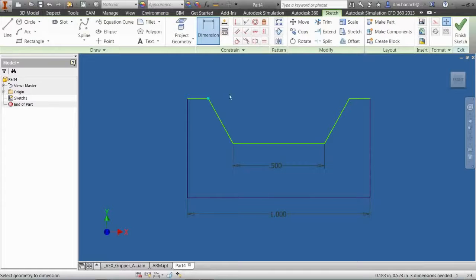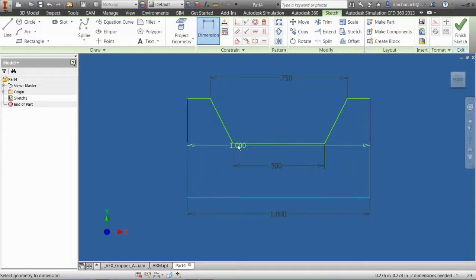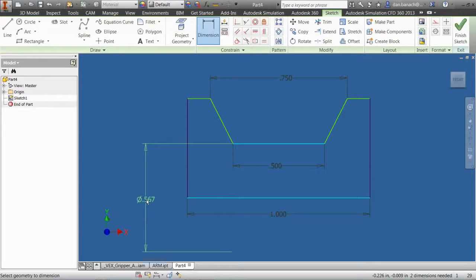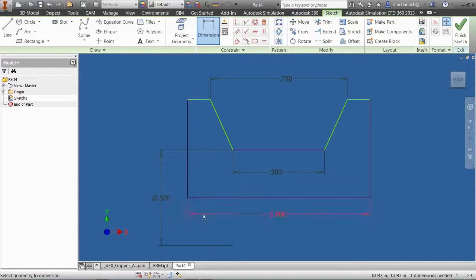So again, maybe the manufacturer is going to give me the outside dimension here. Let's say it's going to be 3/4. So that would work. So I'm going to place in my diameter dimension. That's my goal. But you'll notice when I first select it and it is being previewed, this is actually a radial dimension. So if I were to go back and again revolve this, it's only going to be showing half. But I want this to be a diameter. So one option is simply to do a right click and from the menu, linear diameter. Of course, put that in as a given dimension.